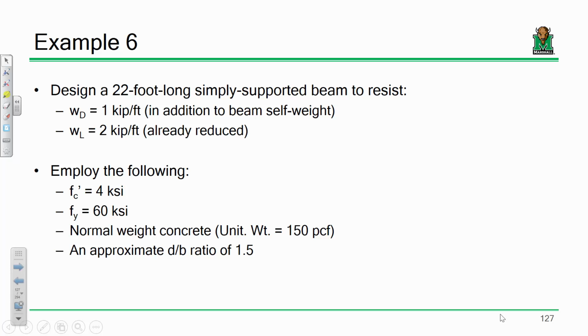There's nothing that tells you in design land that you have to use that. You could tweak that if you want as the designer. Really, the only limit that you have as a structural engineer when it comes to beam depth, quite frankly, is your contractor and your architect. In other words, if you only have, I don't know, 18 inches between that drop ceiling and the next floor, well, you only got 18 inches to put a beam there, so you've got to fit your beam there. But other than that, as long as you're safely resisting the load, that's what matters.